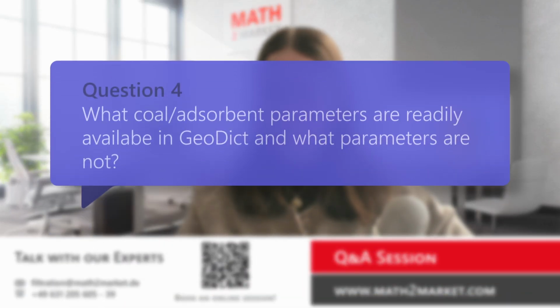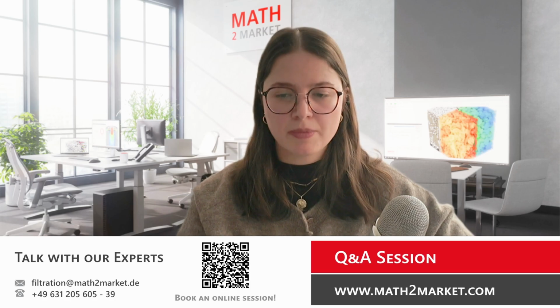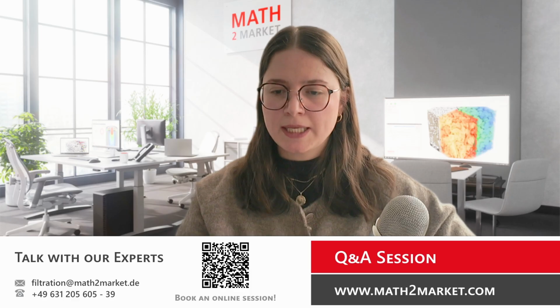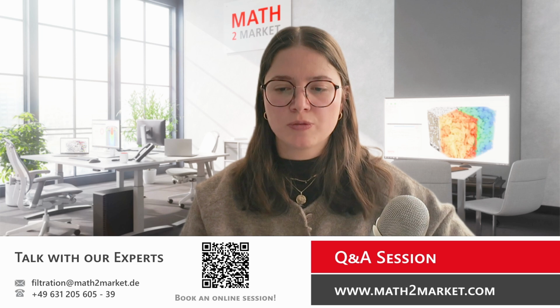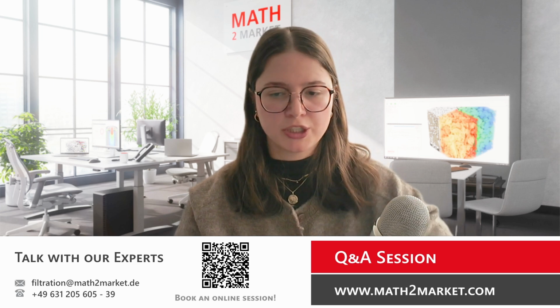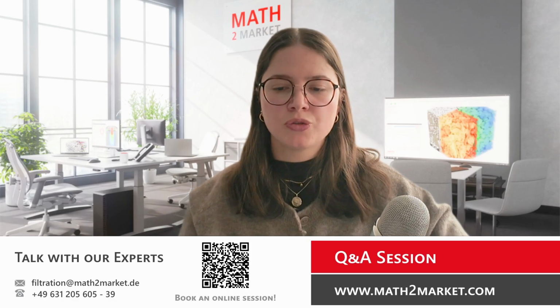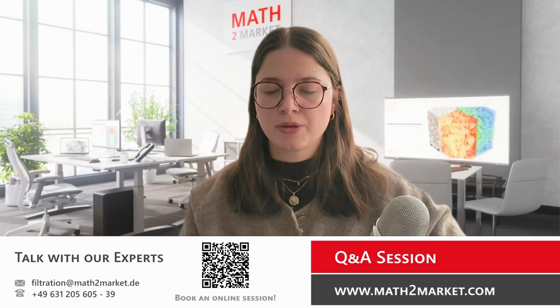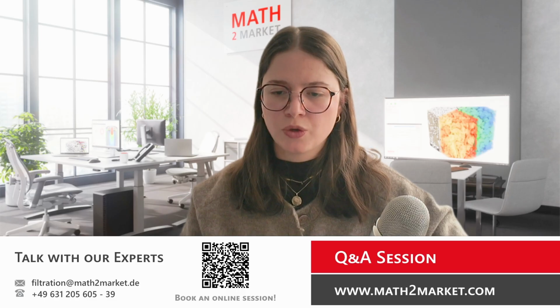Another question is, what coal adsorbent parameters are readily available in GeoDict and what parameters are not? So we have a material database. I'm not sure if I understand the question correctly. We have a material database where you can choose your material from. In terms of adsorption, you choose just a porous material, and then you give parameters to the material, like permeability and porosity. So you have to set the parameters.